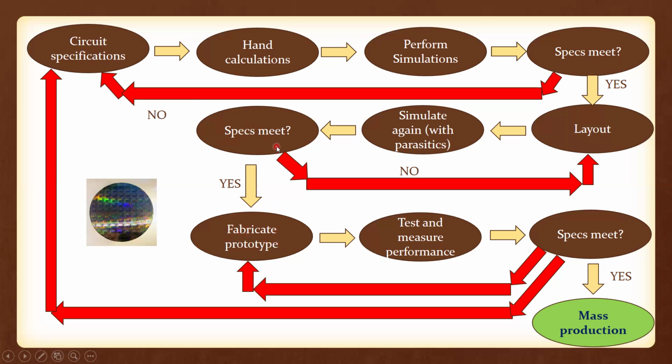However, if your answer to this question, specs meet, is no, then look at this red line again. You go to the layout, you do some adjustment, you adopt different layout techniques. There are advanced layout techniques that help you optimize your layout so that it will meet the specifications.